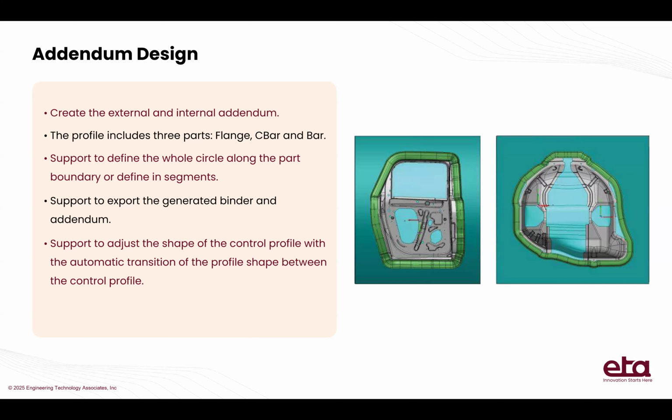Addendum design. This is very important in the die face design. The software can create the external and internal addendum. We can also create a flange, counter bar, and bar profiles, define them globally or segment by segment, or even do a patch between two segments. Export surfaces to any CAD system with just one click.